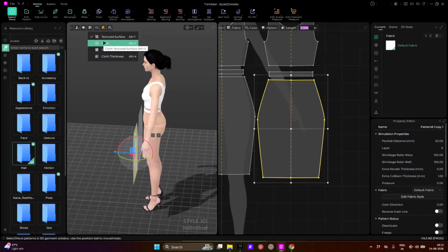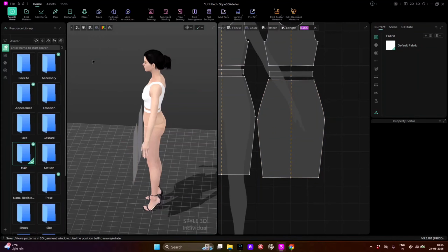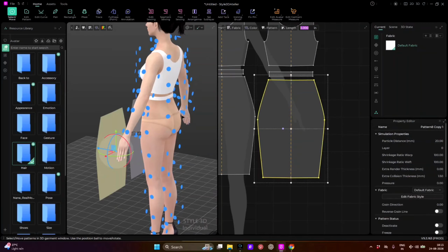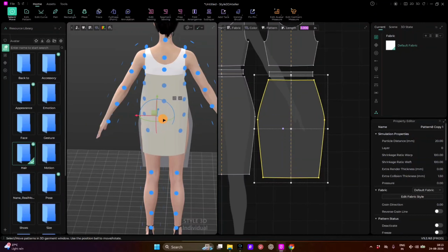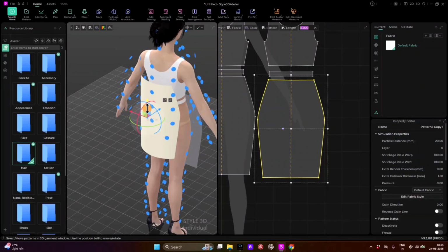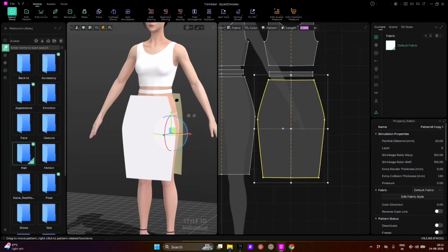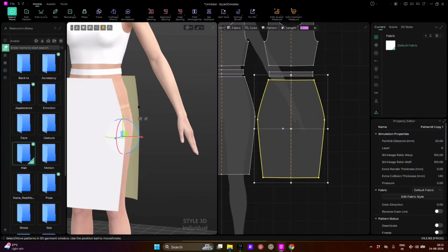And next, we will go to arrangement points again. Select the pattern and place here. Unfortunately, it will place too high, but you have to drag them down. Hide your arrangement points by pressing A again. N means segment sewing stitch.